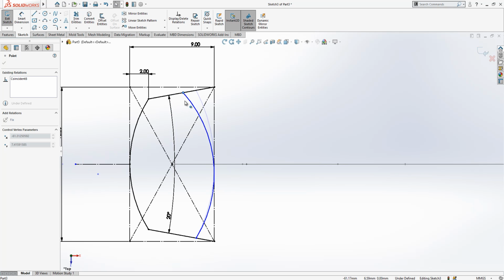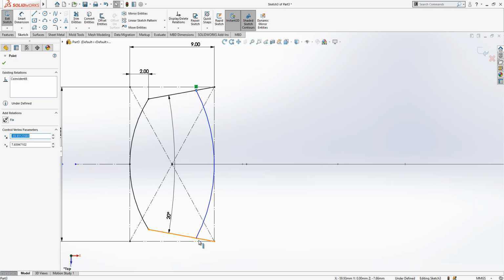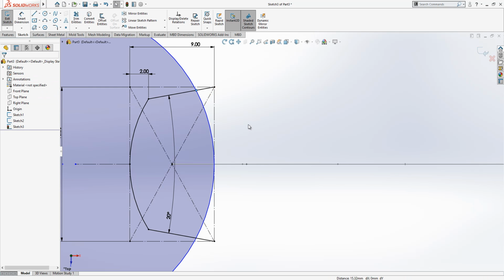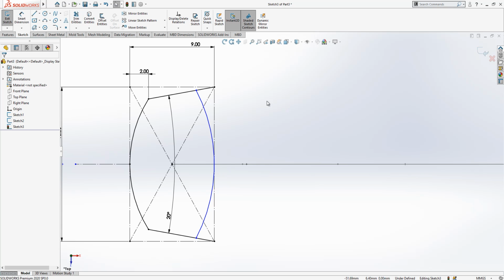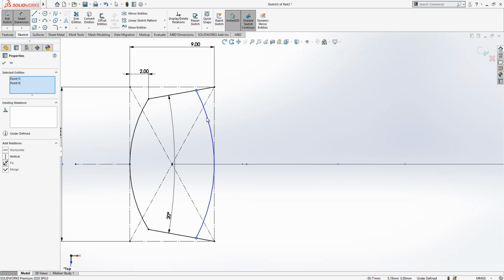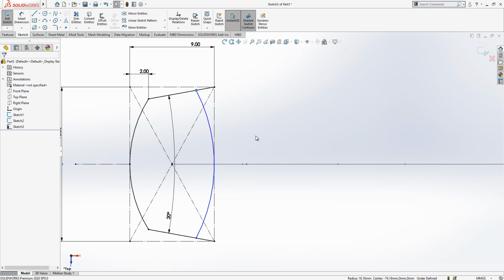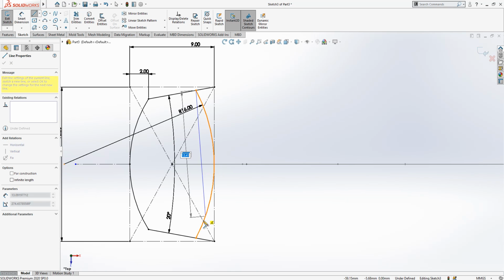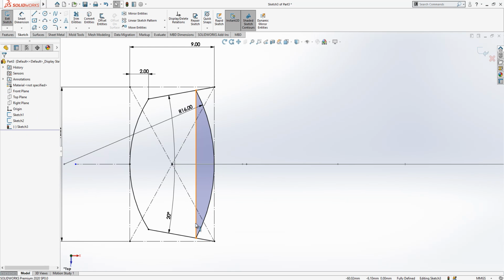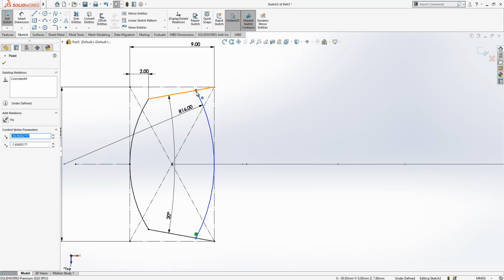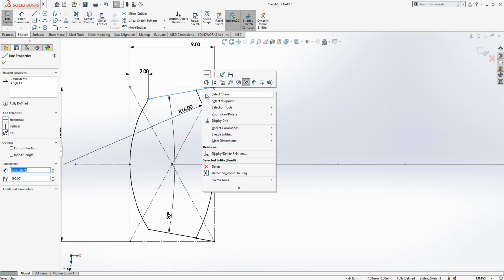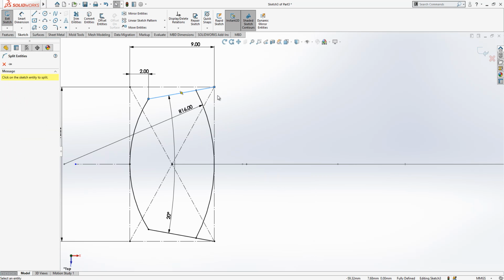Look now, the 2 points are not aligned. What I did earlier, I combined 2 points with a line, but if you want, you can make them vertical. That will help you as well. But let's go back first. Give a radius value. Still, it's not fully defined. Earlier practice was this, which works fine. Or you can select 2 points, Control is pressed, and make them vertical. You have flexibility of doing things.